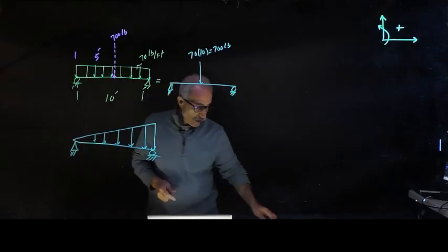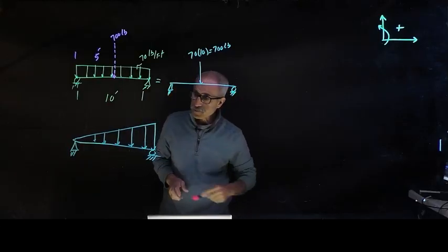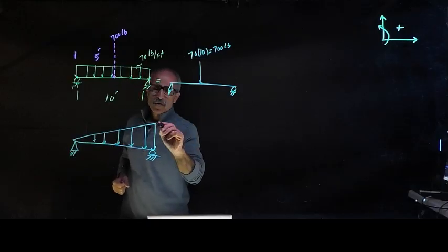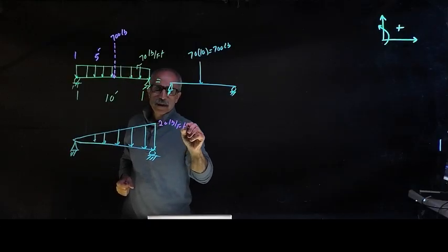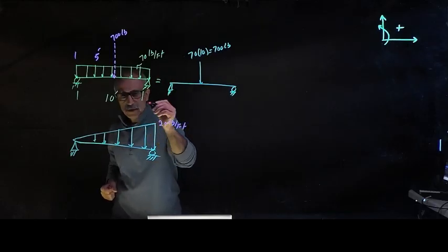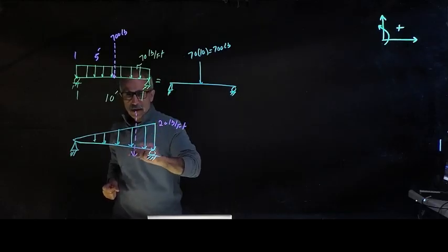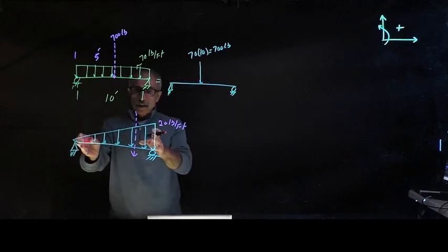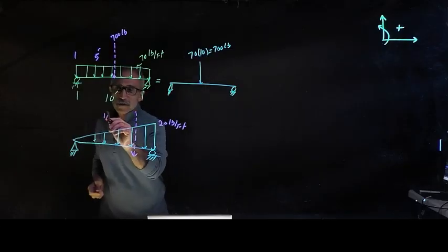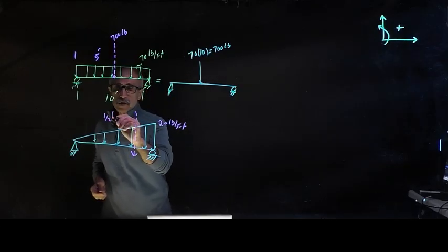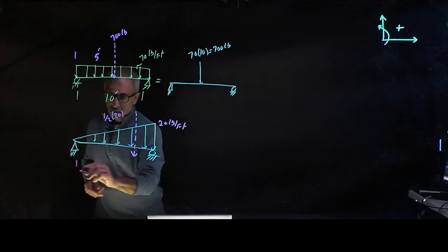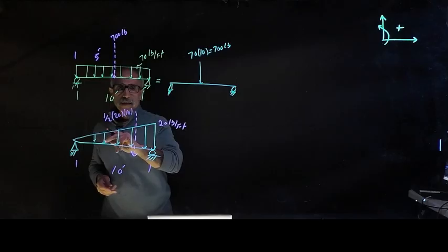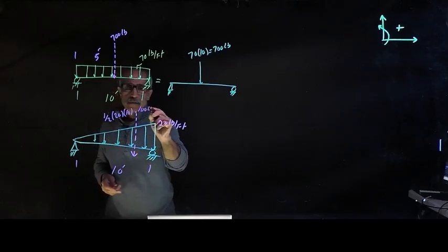So now, again, the concentrated force, and let's make this 20 pound per foot. Okay, so the concentrated force is going to be someplace right here. And what is the magnitude? What is the area of a triangle? The area of triangle is 1/2 base, which is 20, times length. Let's still make it 10 feet, times 10. So 10 times 10, I become 100 pound.